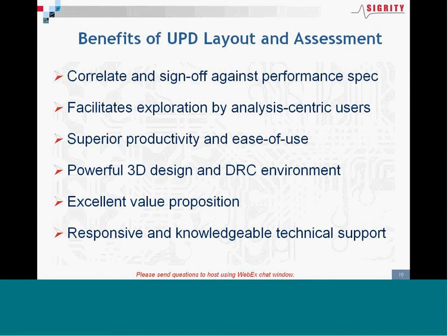The only approximation made in these analyses is for per-pin inductance. Since current must flow in loops, the return for each pin of a given net is assumed to be in all the other pins of all the other nets. Now, this is a technique Sigrity pioneered some time ago for Extract IM and is proven to support electrical performance assessment for a very wide range of packaging families.